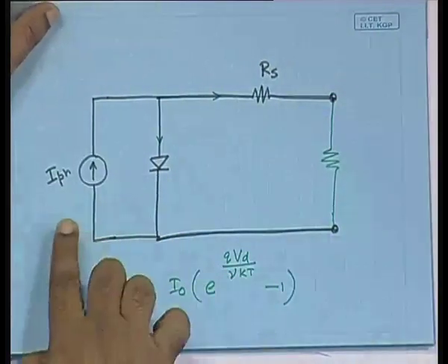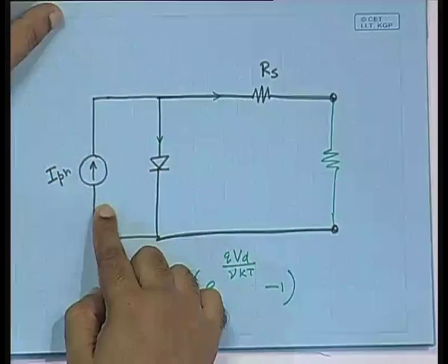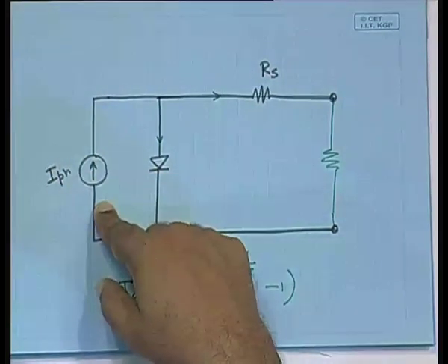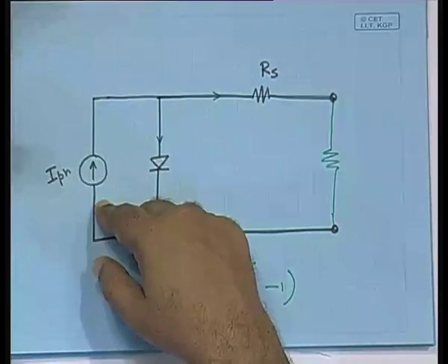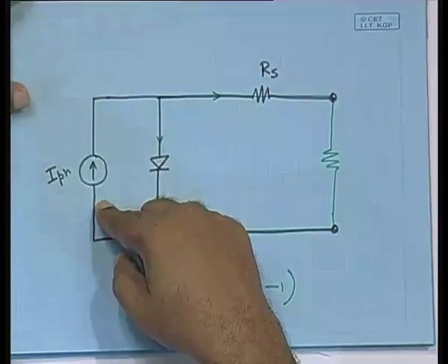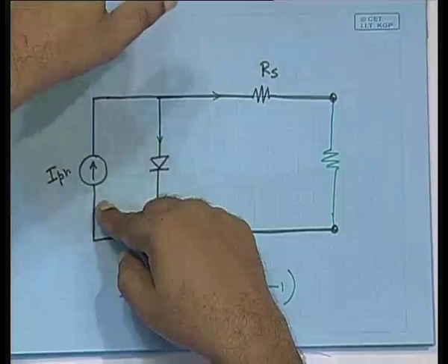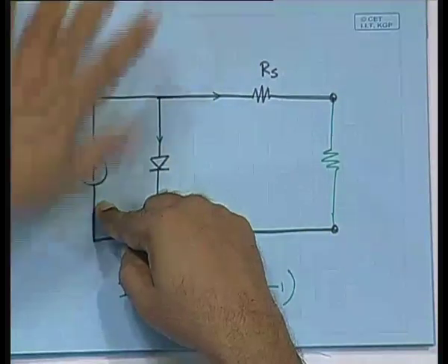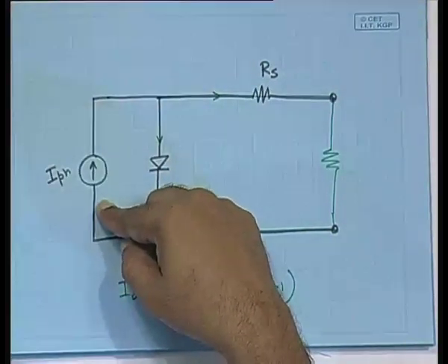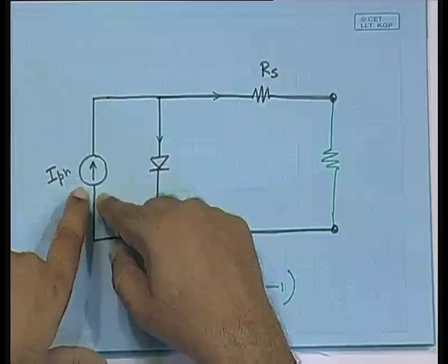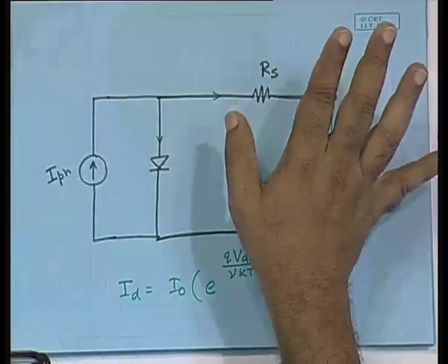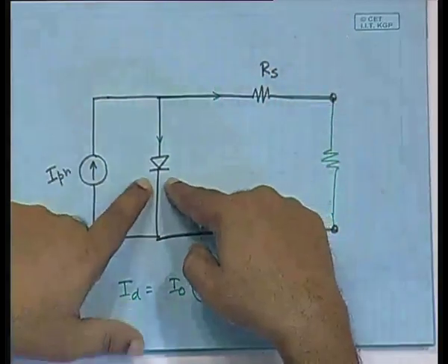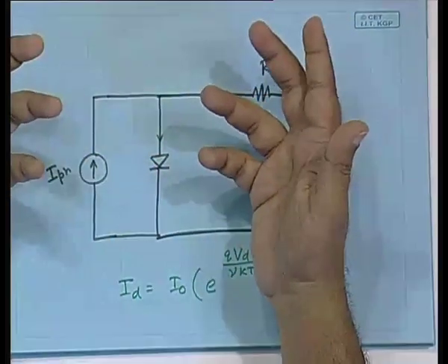It will definitely not be in the change in the IPH, because IPH is exactly related to the amount of photons that are received, the amount of solar radiation that is received. Now, if there is more recombination, obviously it is not the fault of the solar radiation. So, that will not be reflected here. It produces the same amount of electron hole pair generation depending on the energy content of the solar radiation. Will it be reflected here? No, because it is a character of the diode.